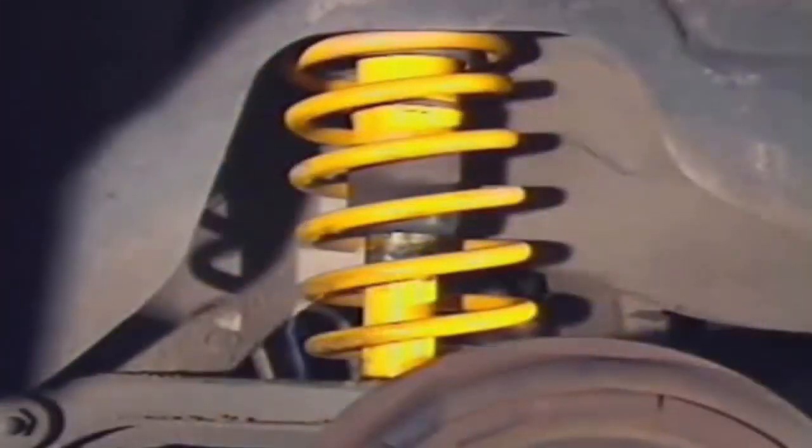To reduce these effects, a manually adjustable air spring can be incorporated into each rear shock absorber. The air spring consists of a flexible rubber cylinder which seals the outside of the upper and lower halves of the shock absorber. The shock absorber is a standard hydraulic type, providing normal dampening action. But when a heavy load is placed on the rear of the vehicle, the rubber air cylinder can be pressurized to assist the suspension springs.